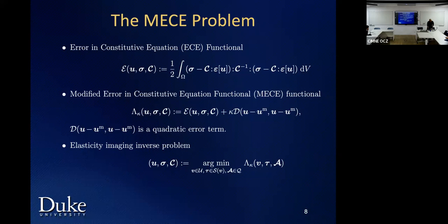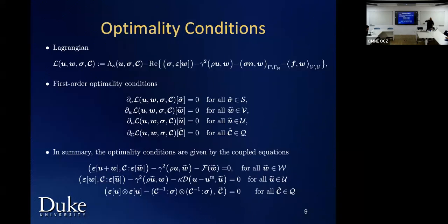I'm going to derive the equations, and I'm going to show you some simple ways to solve this. As I mentioned, there are some things that I will need to assert. I didn't tell you what the test function space is; I'm going to tell you now how you get to that. To solve that optimization problem, you need to find the KKT conditions. So remember, I don't know the stress field, I don't know the displacement. The displacements are connected to the strain; those two are connected in a conventional way. And I don't know the material properties, and I don't know the Lagrange multipliers.